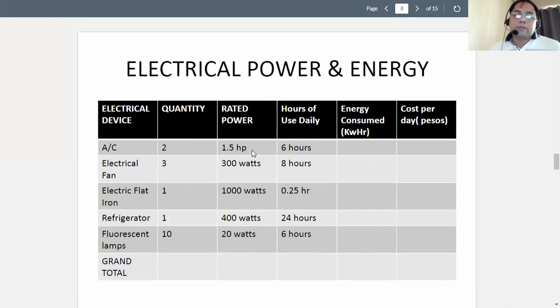So we are going to express all watt values in kilowatt, including HP, and then once we translate all this, we will multiply the number of kilowatt by the quantity. So remember, if there are two of them, then this one will be multiplied twice, times its conversion value of 746. Now, if you change it to kilowatt, then you have to divide it by 1,000. Now again, multiplying these columns will give us our energy consumption.